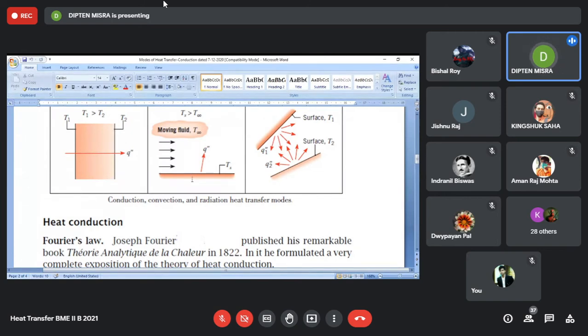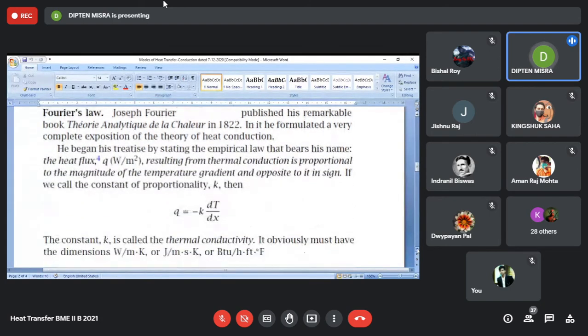So the only way the heat passes from the wall through that particle to the next layer of particles is by conduction again. Even though the bulk of the fluid is participating in the convective motion, the fluid particle sticking on the wall also participates in the heat transport from the wall into the mainstream, and via that particle the movement of heat is because of conduction. So we can apply the same law of heat conduction to that particle also. So the heat which is